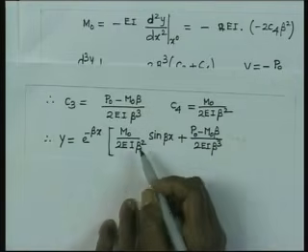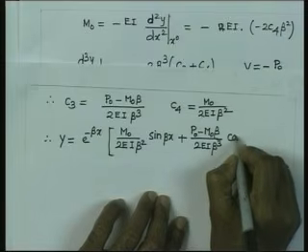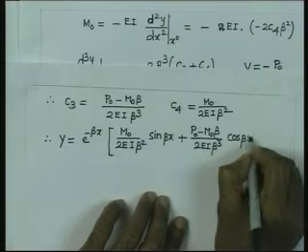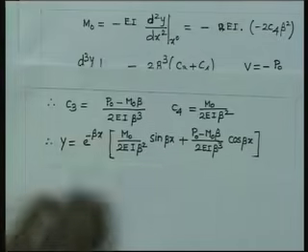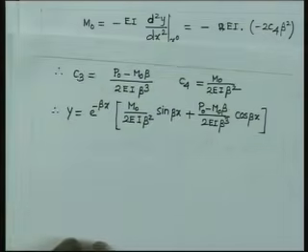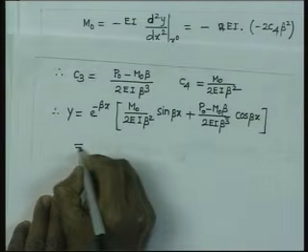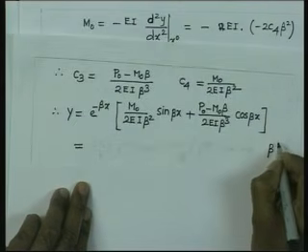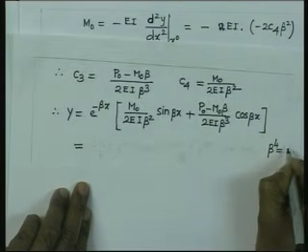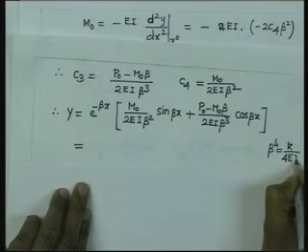So, we have substituted the values of C3 and C4. So, that is the expression for the deflection, and we can recombine these and write the value in terms of k, because beta to the power 4 is nothing but k by 4 EI.